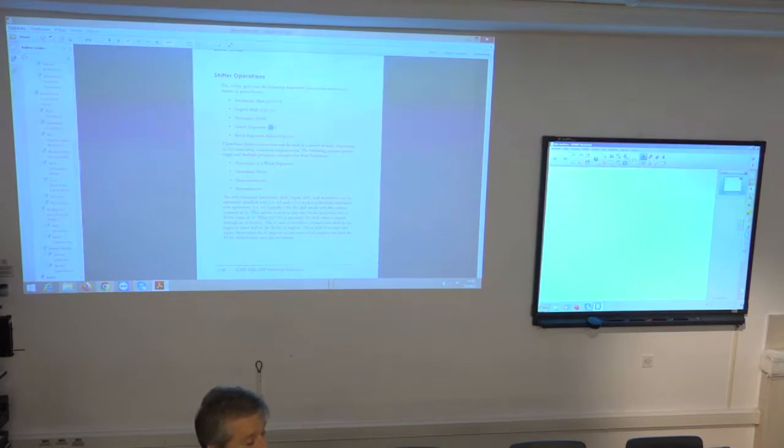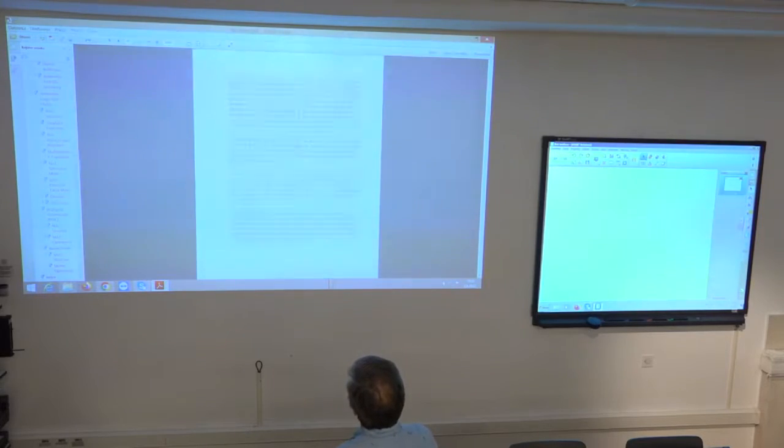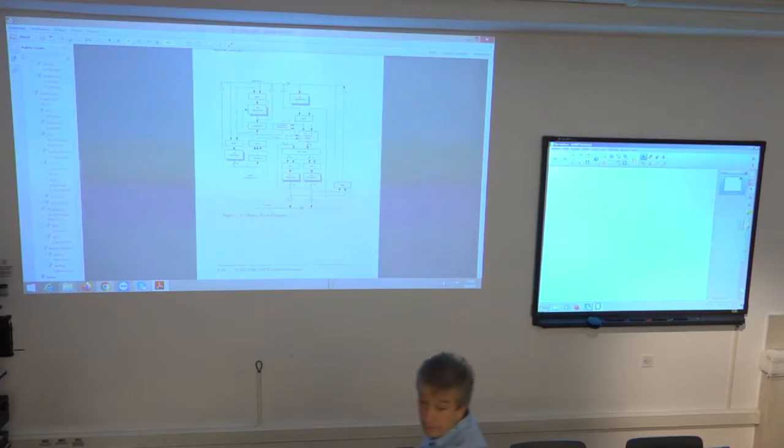It performs the left shift with a negated value of the SE register. That is the reason why in this architecture you have this negate. The negate is activated only for the normalization instruction. For a normal shift instruction, you simply pass the SE register directly as a control input to the shifter array.